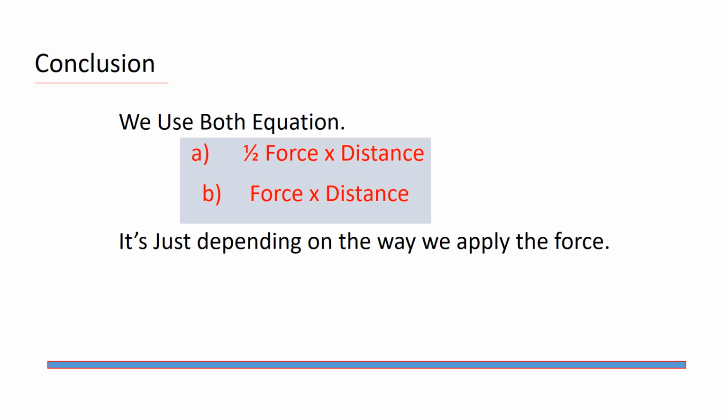Work can be expressed in terms of energy. The unit is kilonewton meter, where 1000 joules is 1 kilonewton meter. In rotation, work can also be defined as a moment multiplied by rotation, M theta, as we saw in my previous portal frame analysis, where M is a moment acting on the structure and theta is in radians.